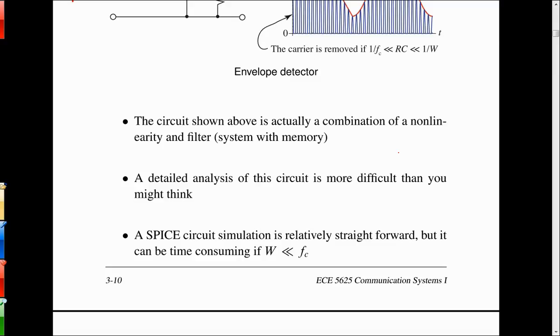And if you have A to D circuits involved in digital processing, then it's even more of an issue, because you've got to make sure that the amplitude level that hits the A to D falls right in the dynamic range of the A to D. You can't have it be too tiny, or too big, because you lose out either way, either getting too much quantization noise, or you're saturating the converter and then it's clipping, and that's ugly too. So it's not something that has gone away.